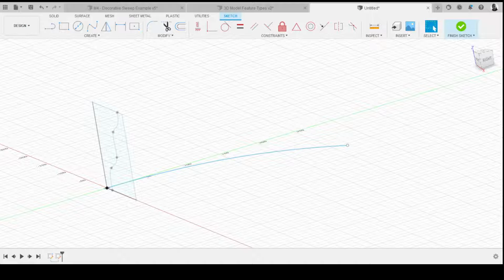You can also, we probably won't have time to look at 3D sketches as well. So you can do a 3D sketch and your sketch doesn't have to be just on a plane, as long as it's still connected and that sweep can run along that 3D sketch, you could do that as well. So it just uses the edge? Yeah, it just uses the edge. Any edge as long as they're connected. Exactly. And if you've already got a piece of geometry, say you've already got a body model that's already there, you can use a line that's on that piece of geometry as well, so as long as it's connected. If you had a tabletop, for example, you could use this to do your router edge design. And then sweep around it. Absolutely. That's a good use of a sweep, especially if it's a curved table or something like that.